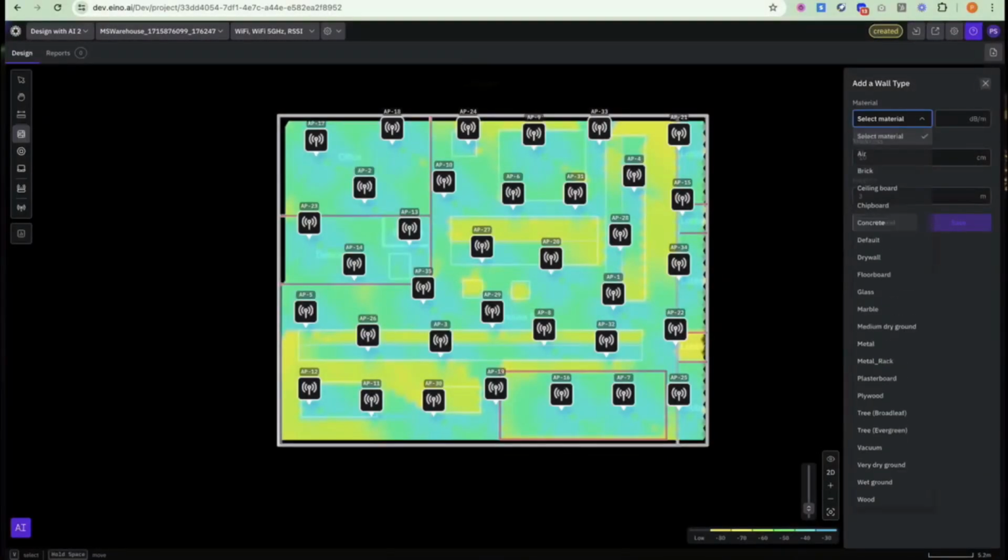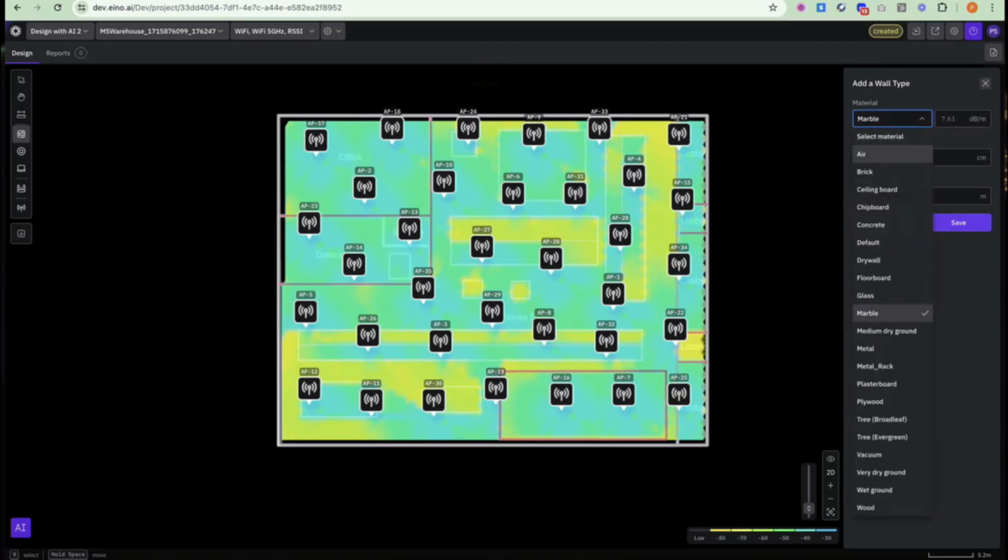Yeah. Good. Where did you get the input for the wall RF attenuation? We do have a database that basically has all these different materials, and then it does calculation frequency dependent. Here we just show it for 2.4, but the backend understands that, okay, this is the material, and according to ITU standard, what are all the factors? And if I send a 5 gigahertz or 2.4 or a cellular, how much my attenuation per wall changes, and yeah, it does all of those calculations.